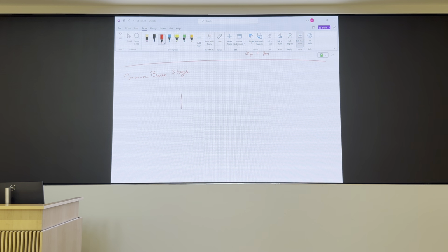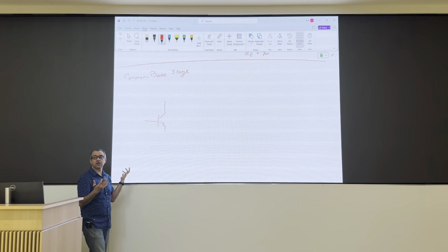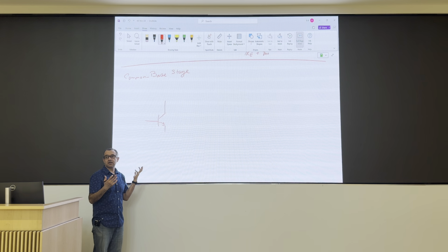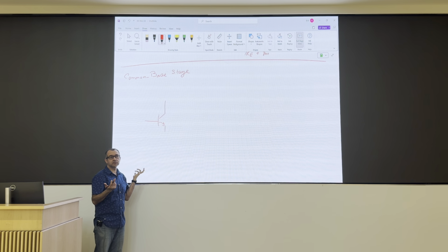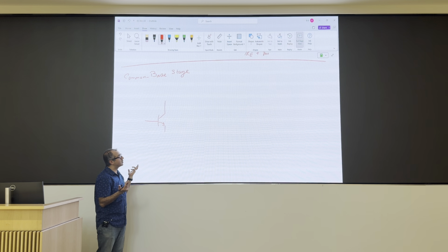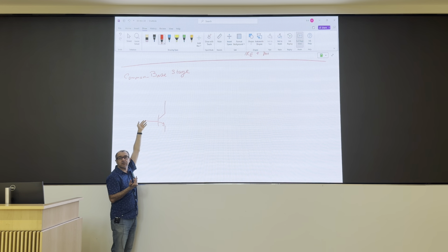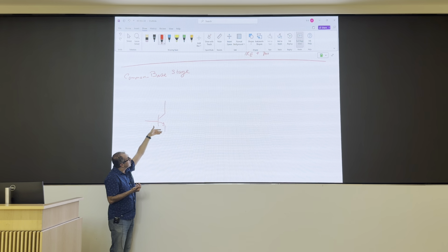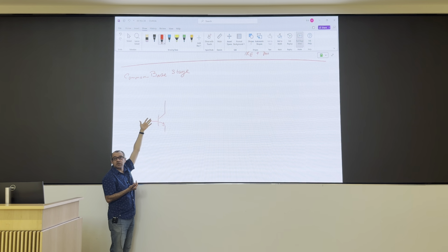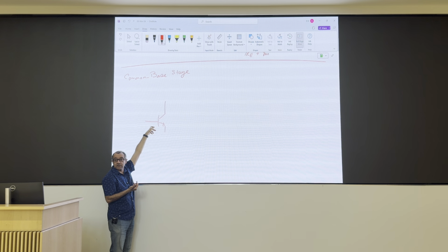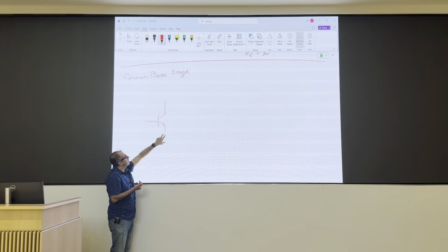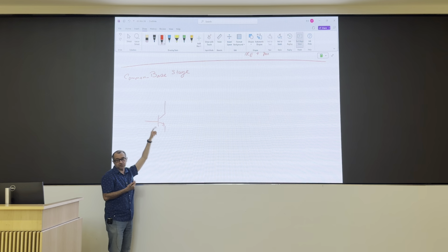And here is my transistor. So tell me, how do you think the input and output are connected? Input is to collector or emitter, because common base means that base is not in my signal route. So, emitter or collector for the input? Emitter. We never connect an input to a collector. So, input to the emitter, output from the collector.